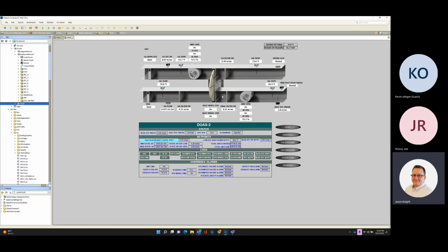This heat wheel, it's going to run. This is the only type of heat recovery you actually have, or cooling recovery, right? It's sucking air from your building into these honeycombs and capturing a portion of that air, and then your outside air is being sucked through from right to left, and then it's hitting. Let's say it recaptures the 72-degree air, and let's say your outside air is 95. It's going to temper a little bit with whatever's recaptured from this wheel and push it back through.